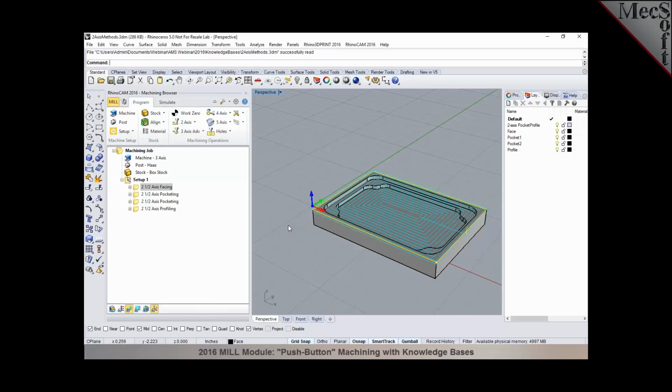Well, with the selection rules, if you have it set to use geometries like arcs, circles, rectangles or curves, then it would definitely work. But if you have layers, since layers are only applicable in Visual CAD and Rhinoceros, the knowledge bases can be shared between Visual CAD/CAM and RhinoCAM, but a knowledge base without layer information can be applied to Visual CAM and SolidWorks as well.